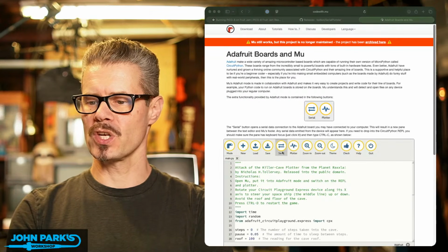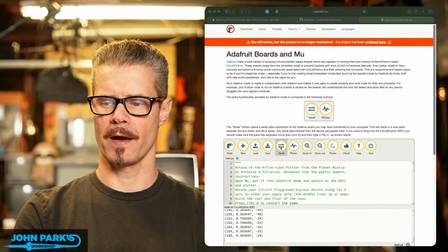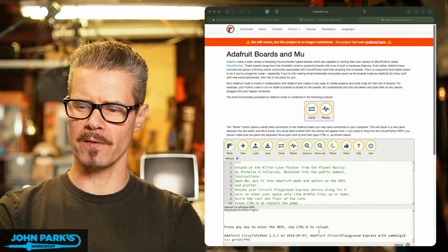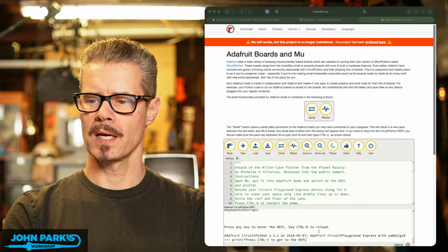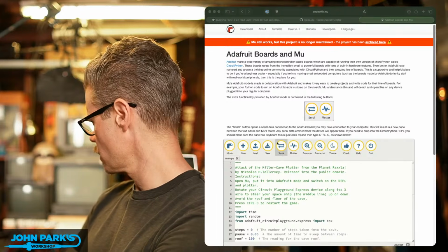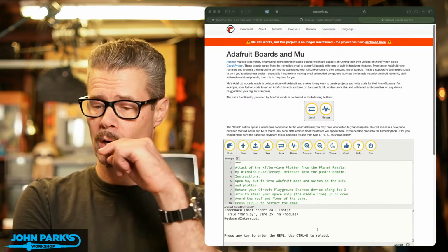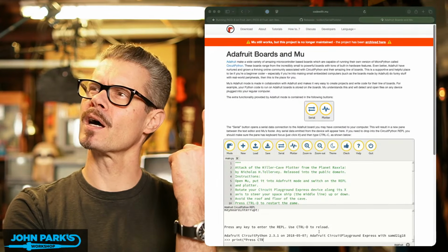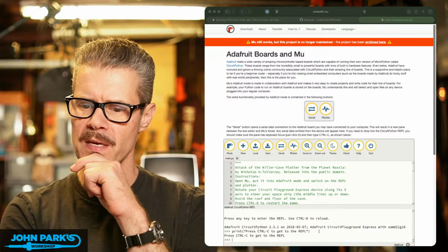Gordy G says, can the Fruit Jam handle a USB hub? I have not gotten hubs to work on Fruit Jam, or I think any of the CircuitPython RP2350 boards, like the Feather, that have a USB host. I think the two ports on the Fruit Jam are going through a host chip. But I have not gotten keyboards or controllers to work through a hub on either the Pico Nest projects. I don't know if I've tried it on Fruit Jam OS, but something about it confuses it.